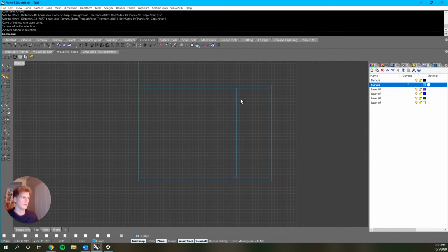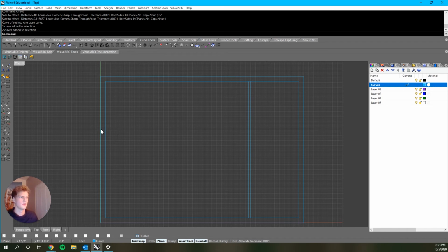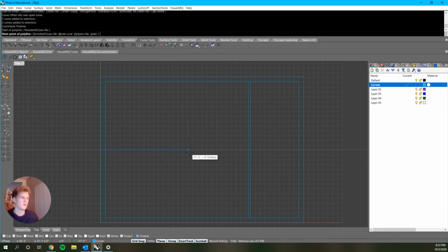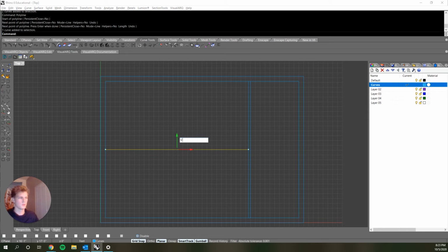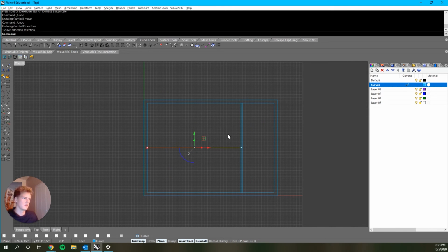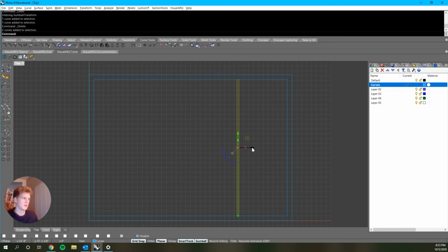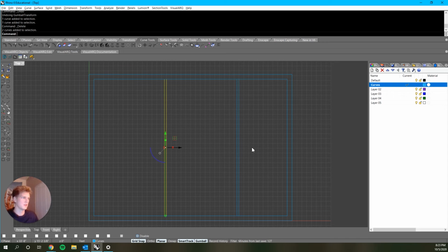So now you're starting to get an idea of how you can start to actually draw a plan in Rhino. If you want to make another polyline, type polyline. Using your snaps, you can find the midpoint of one of these rooms. You could move it over and then, of course, do the similar thing. Just make duplicates all you want. Maybe you make some 5-foot spacing or what have you, but you can start to actually define the sort of elements of this space. We could make another duplicate over here that's 15 feet.